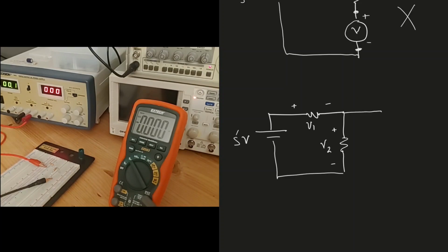So the idea is that I'm going to connect something over here. Let's say this is my voltmeter. I'm going to connect a voltmeter between these 2 points, but this meter should not draw any current from the rest of the circuit. So the current that is going to flow through the meter should be almost zero, meaning it should be very, very small. And this can happen if you can imagine that there is a resistance which is very large. So let's say approximately almost a giga ohm, right?